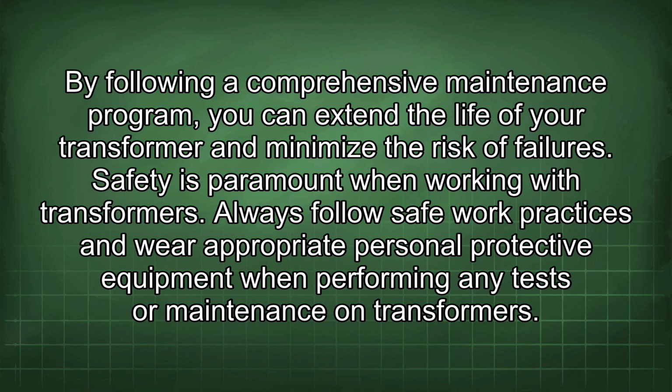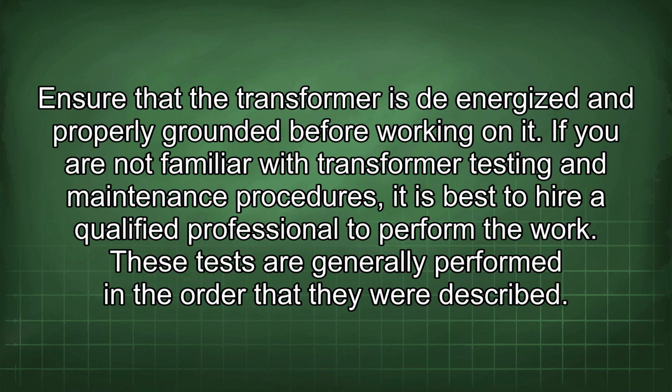By following a comprehensive maintenance program, you can extend the life of your transformer and minimize the risk of failures. Safety is paramount when working with transformers. Always follow safe work practices and wear appropriate personal protective equipment when performing any tests or maintenance on transformers. Ensure that the transformer is de-energized and properly grounded before working on it.